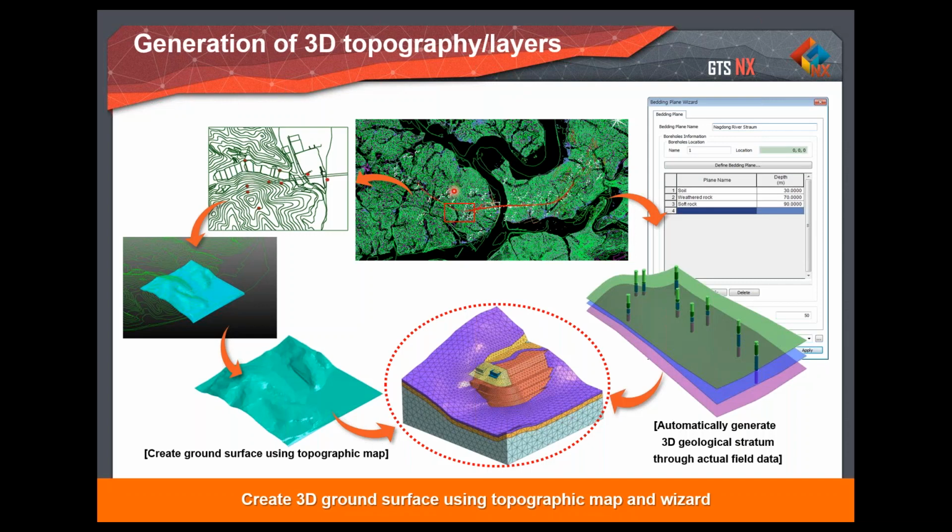So what we do to overcome this is take the contour map of this particular area. So this is my contour map, and using this contour map, we develop a surface. This is a surface that was developed using the terrain geometry maker, and using this surface we develop the model. This is very simple, and completes within about 2 minutes. I will be demonstrating this terrain geometry now.